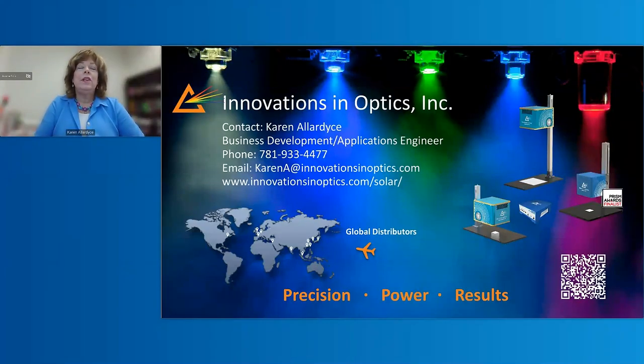Okay. So I touched on it briefly, but without an imaged field, you can have severe fall off in uniformity as you move off the nominal working distance. So if your sample changes height, or if you're going to go to a different depth of sample height, any height variation ruins uniformity. Also, wavelength uniformity is poor, and calibration is much harder and less stable. So the imaging system, like what we use in our LumiSuns, gives you depth of focus, basically, and so more tolerance on sample positioning.